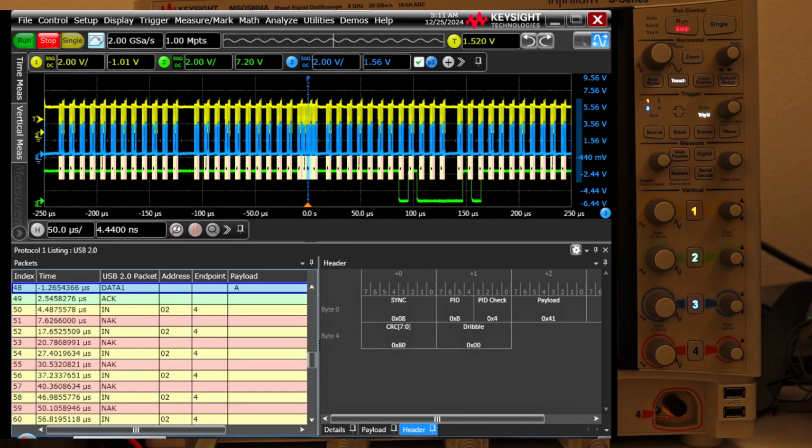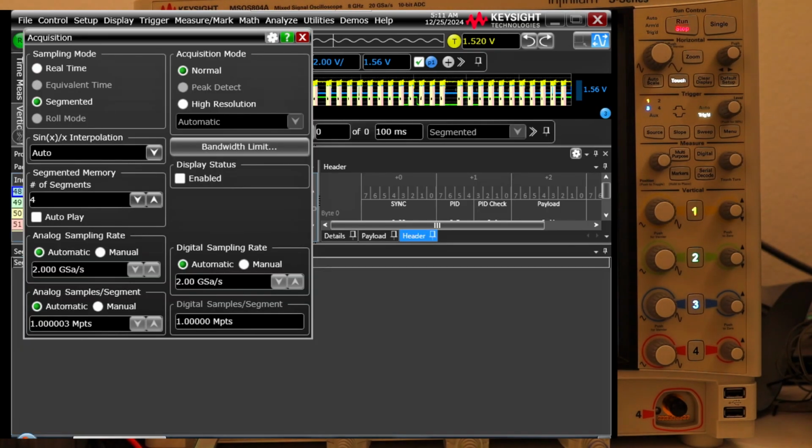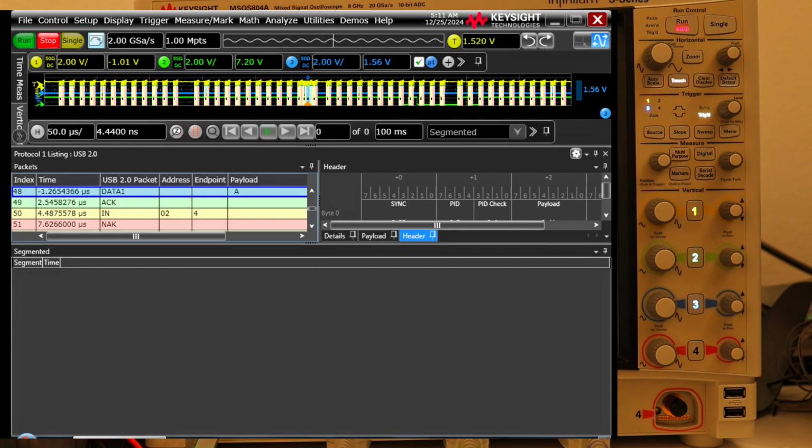processing for the display. So now this oscilloscope has a really decent feature, and it has a segmented memory. I think all the good Keysight oscilloscopes have segmented memory. So we'll set up a segmented memory now. We need maybe 4 segments. Can we go down? We can go to 2, maybe 4 segments are enough, yeah. Everything else remains the same.